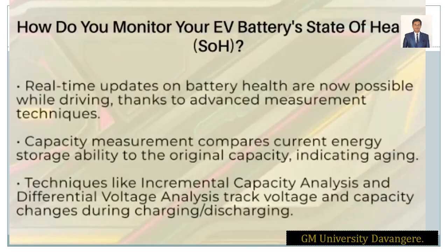All right. Now we have the various techniques: incremental capacity analysis and differential voltage analysis. We track the voltage and capacity change during charging and discharging. These are the methods by which real-time updates can happen while driving also. You also have to think about the advanced incremental techniques, that is ICA plus AI, incremental capacity analysis plus artificial intelligence.